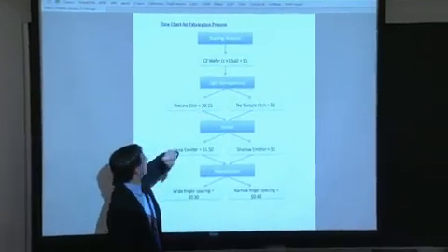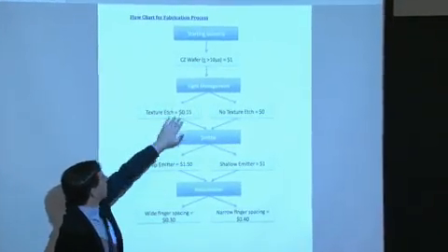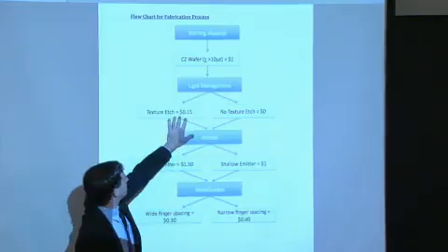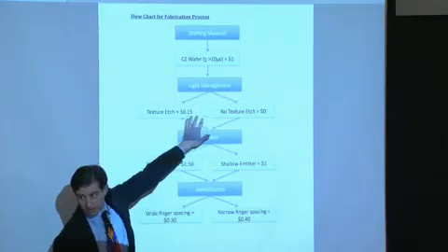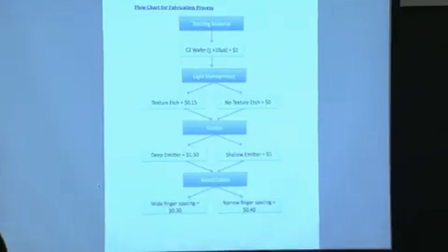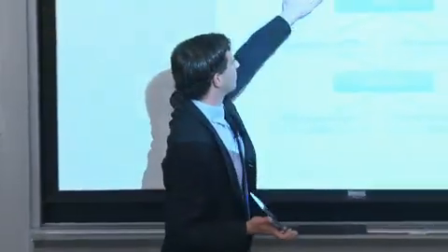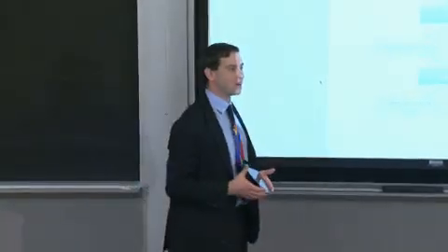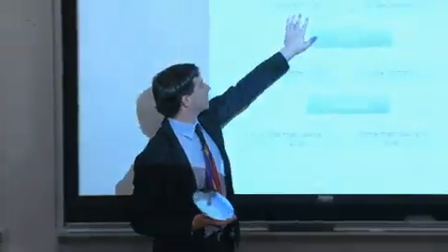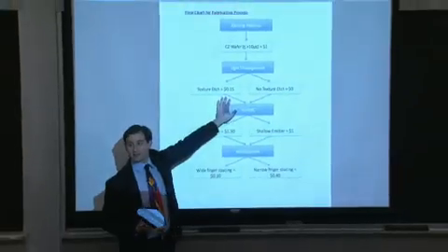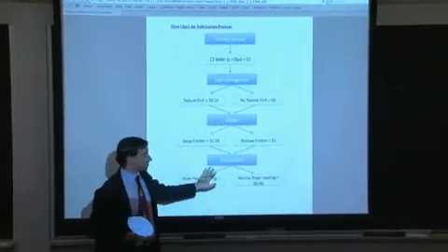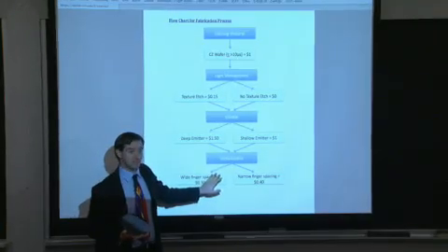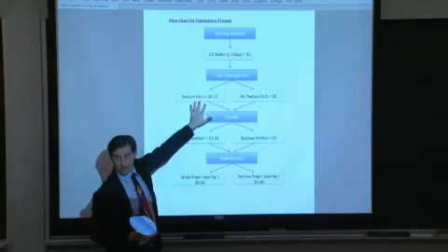You'll start with a wafer. It has a certain cost associated with it. You'll have some decisions to make concerning light management, whether you want to texture your front surface or whether you want to leave it bare and reflective, like this right here. Whether you want a reflective front surface or you want to texture it, there's a certain cost associated with it. So you can probably go to some online resource like PVCD-ROM and use their simulator or the one you've already constructed for homework number 2 and calculate what the predicted efficiency boost should be if you texture your front surface. Keep in mind, in this very simple solar cell, we have no anti-reflection coating. So the texturization is pretty much all you've got for light management.